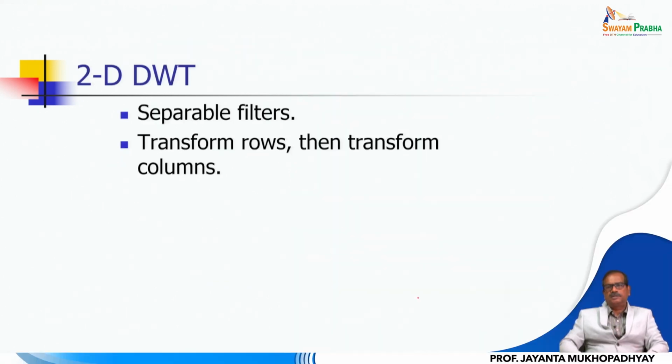So when you talk about two-dimensional transforms for wavelets, it is the same features or properties of the functions that we have used, like the separable property, that makes the extension to 2 dimensions convenient. So you can again think about separable filters. Your basis mother wavelets simply get multiplied in both the domains. They generate 2-dimensional mother wavelets.